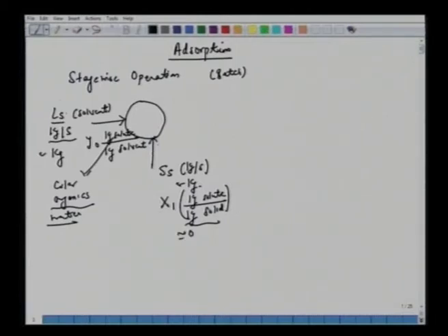So you bring essentially a solvent with adsorbate. The adsorbate will be this solute dissolved in this aqueous phase, some liquid here. You bring it in contact with the adsorbent. The adsorbent may be fresh or may contain a very small amount of this solute. Then you bring them in contact, and finally you withdraw this treated solvent or feed.